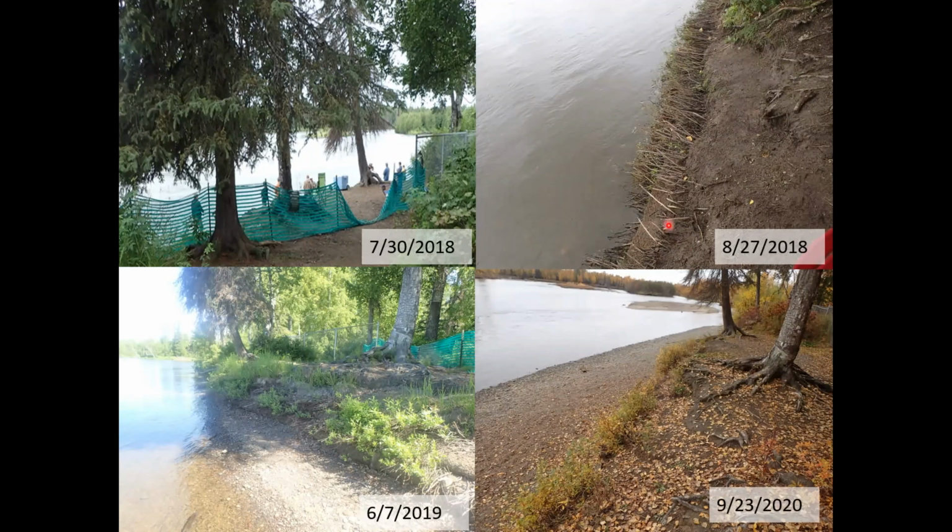A lot of our willows didn't survive just because people were walking on them and they happened to sustain some high water. So a year later, June of 2019, we got some willows to come back and survive. We've got some grasses starting to come up. And then September of 2020, you can't even tell there's vegetative mat, but we still do have some willows surviving. So in this case, it would have been good to think about maybe we need to add some access stairs into the creek, or start thinking about, this is a heavily used area. How can we best manage and protect our bioengineering that we just installed?